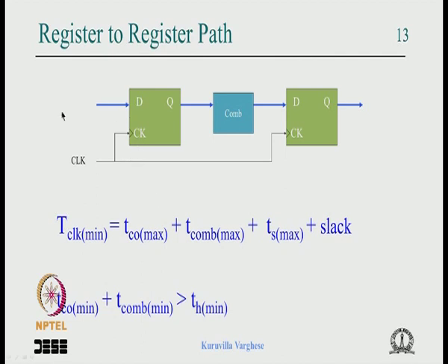Similarly you have a path here that terminates at clock bar, and another path here which terminates at clock, then both outputs go to another register, then you are confused whether that should be clock or clock bar, but it cannot be both, then you are stuck.